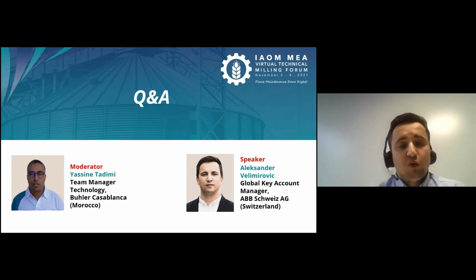So if you have an IE4 motor and you rewind it, most probably you will lose maybe 1 or 2%, or 3-4%. It depends on how good the rewinding shop is. Not everybody uses the same copper and materials, and it's very much a case-by-case issue. Very professional rewinding workshops can deliver the same quality, but there are also, as everywhere, bad quality materials and shops. Then you have a motor which does not have the same output power and has lower efficiency.